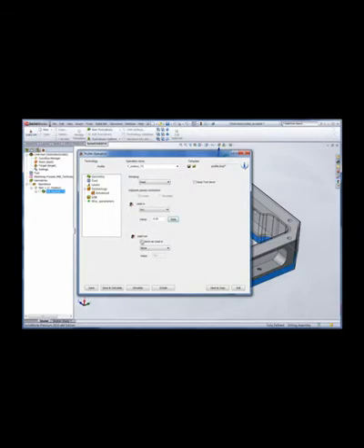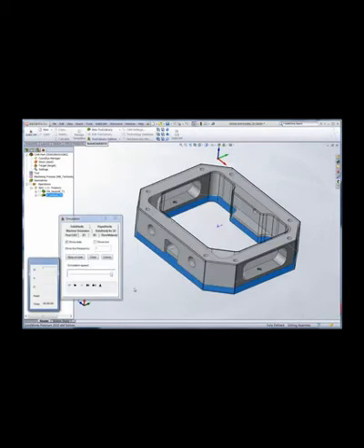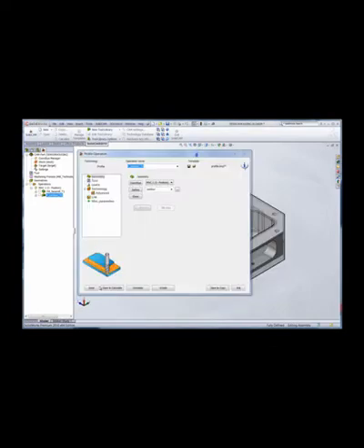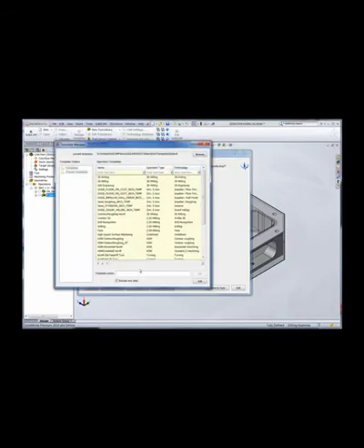We'll use a 250 radius arc with a 45-degree angle and a G41 application distance of 10 thousandths. We'll use the same settings for the lead out. Save and calculate and simulate, and again you can see how quickly SolidCAM generates this toolpath.